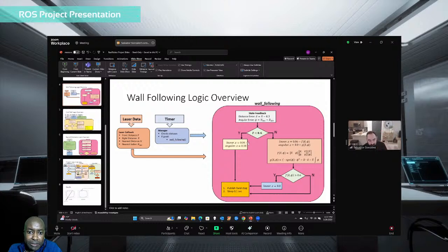What would happen is that the error evaluations would change very quickly, and it would stop moving, and then it would have a dramatic increase in the angle turn. So it was like a hard stop, more or less. It was an aggressive command, and when I tried to make it calmer, I found that the rest of the wall following behavior itself wouldn't respond as well.